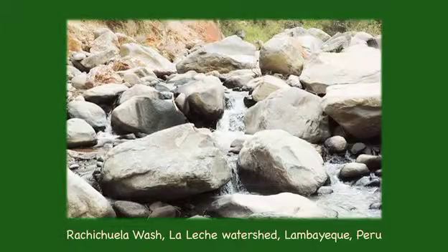Channel gradients are directly related to bottom friction and inversely related to flow depth. Typically, bottom friction increases and flow depth decreases in the upstream direction. Conversely, friction decreases and flow depth increases in the downstream direction. Channel gradients vary widely, from steeper than 0.1 in typical mountain streams to as mild as 0.000006 in some estuarial rivers.